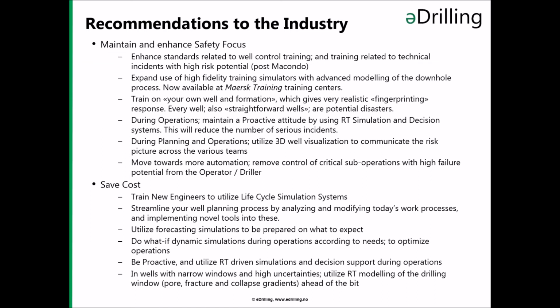The next point is to expand the use of high fidelity training simulators with advanced modeling of the downhole process. I think this is also linked to the first point. And now the most advanced simulators in the world are available at most training centers around the world. The third point is that I would advise operators to train on your own well and your own formation. This gives a very realistic fingerprinting response. And we should not forget that every well, also the so-called straightforward wells, is a potential disaster.